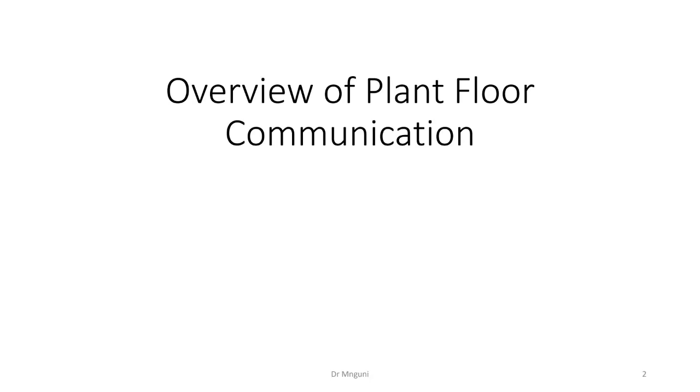I was speaking about the 3 levels that we work on. Level 1, which is your instruments. Then level 2, which is your controller part, where the instruments are feeding information to the controller. The controller needs to make a decision and then send it to level 3, which is your final controller part, where you find your actuators and so on. The muscles to do correction.